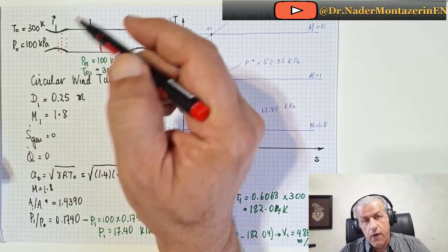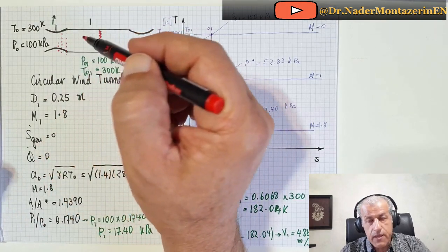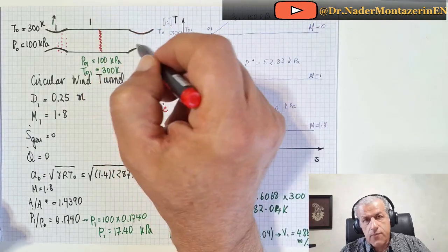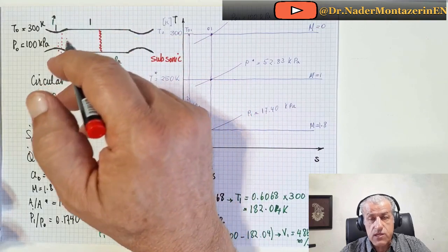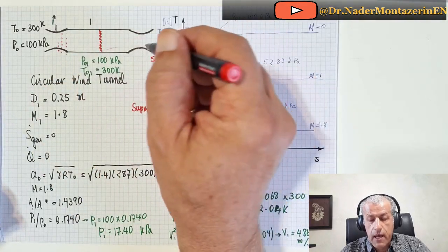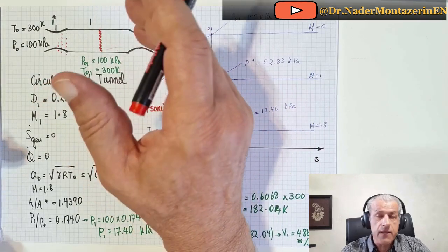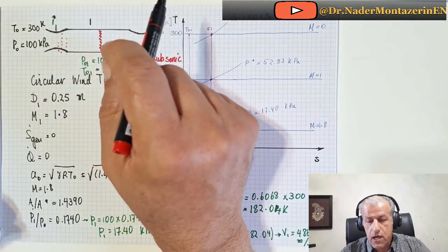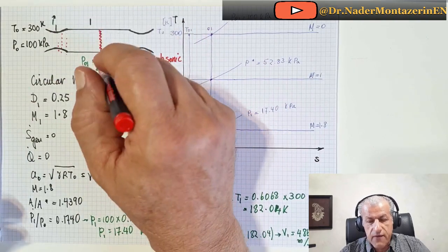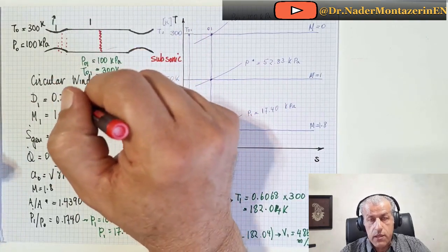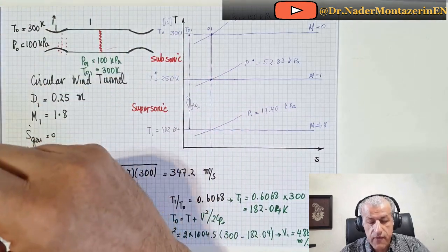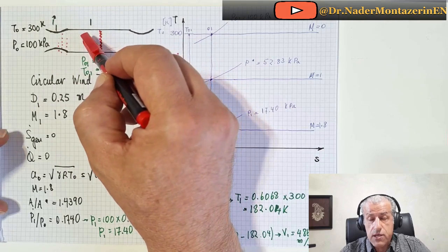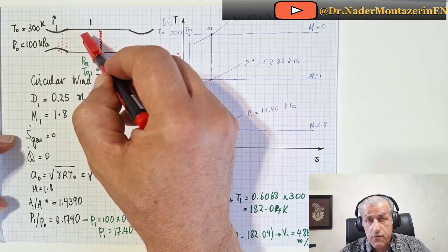And of course, it's ideal if this shock is swallowed out, like it was disgorged from here, and we had isentropic flow. But there are points in it that you have to take care of. Let's see what happens if there is a point 1 here, and there's a shock wave, and the entry Mach number to the shock wave is 1.8.